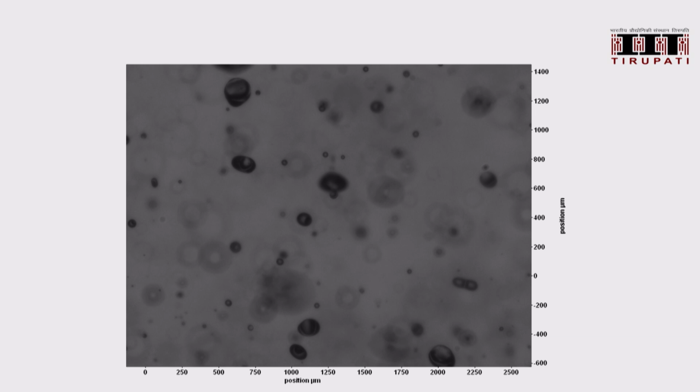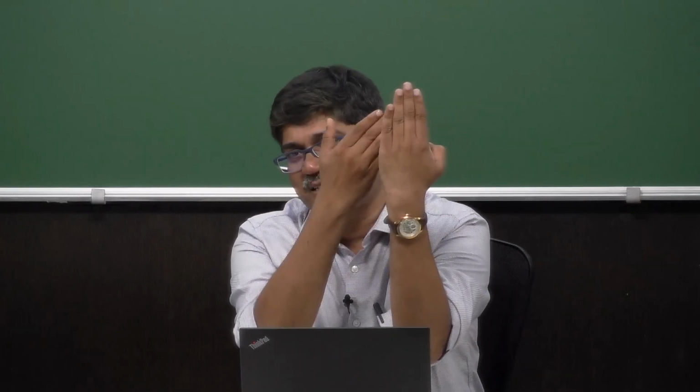Now if we take one more image after some delta t, the drop's position will have moved slightly. Now I can correlate these two, this is frame 1, this is frame 2. In this time, it moved by this many pixels or this much distance. With delta t, I can get the velocity, right?